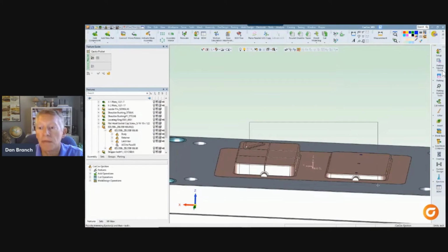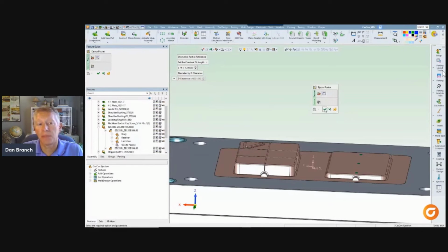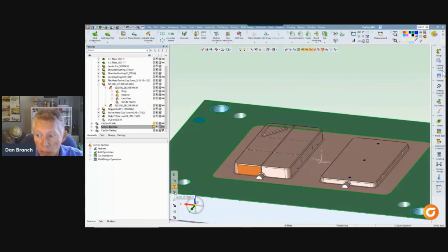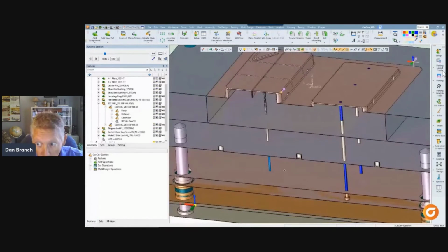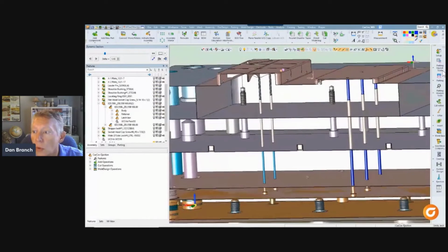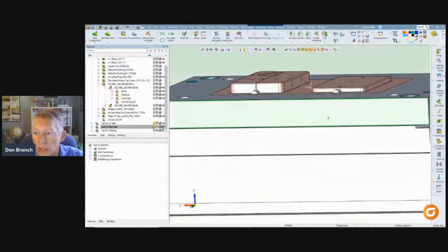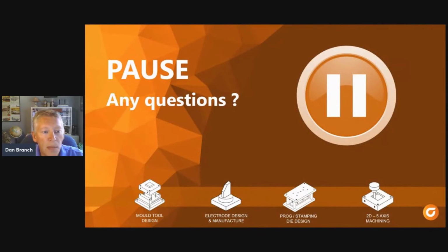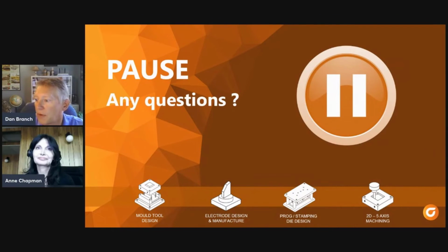And then there's another function for doing the ejector pin holes. Now, these holes get a special function because it's nice to have some extra options for them, like varying the depth of the clearance drill hole back from where the pin's going to break out on the part. So a quick section view with the hatching turned off is a good way to see how those holes turned out. And you can see all the different clear and fit diameters. And while we do have more to talk about, now seems like a good time to break for any questions that have popped up.